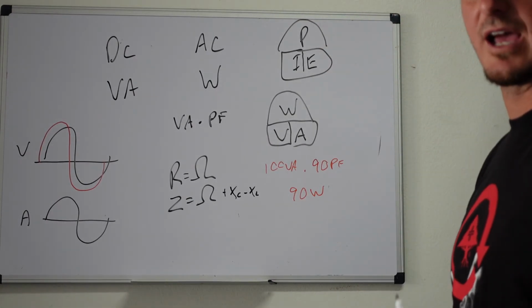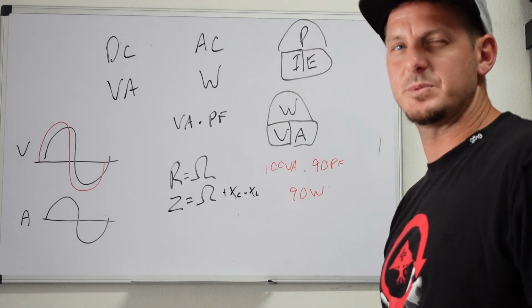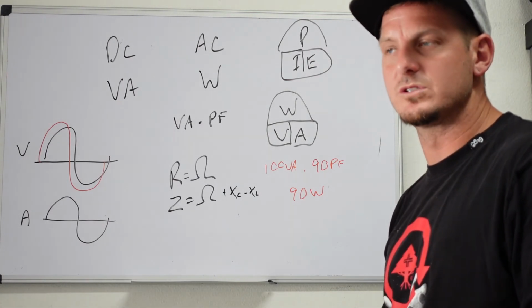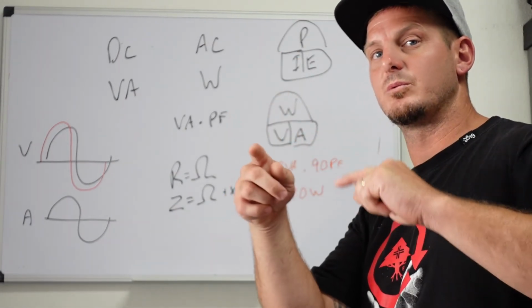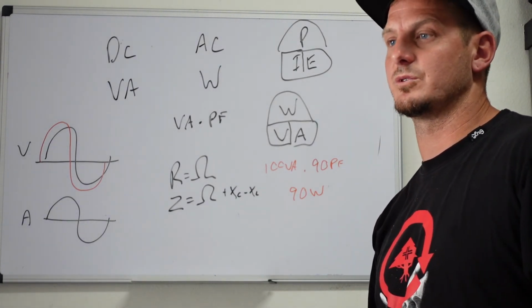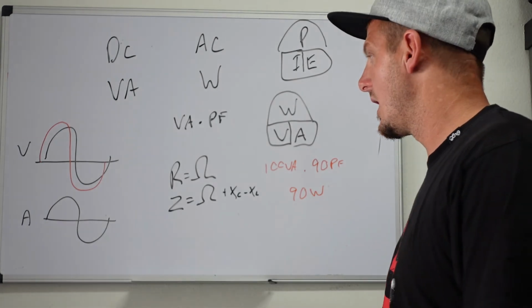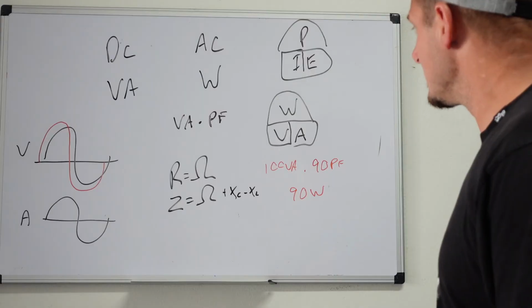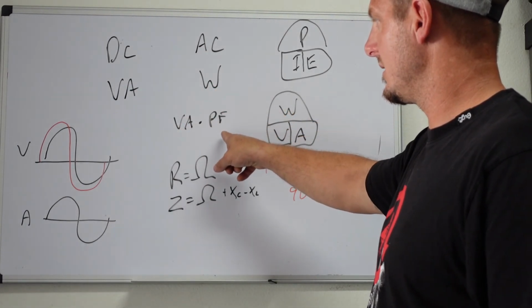You're generally going to have more inductance than you are going to have capacitance, and that's because you have more inductive loads. When you wire a house, you will make loops. Any loop will cause inductance to happen. You have transformers which use inductance by nature, but that's exactly what it is. It's an inductor. So when you see watts, you got to remember it's VA times PF.